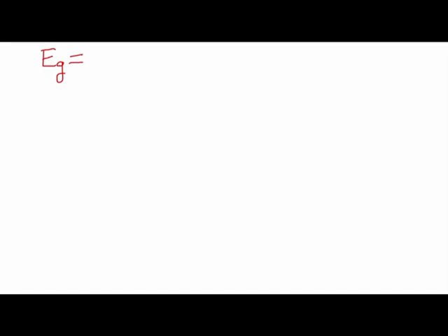That is 541.67 volts. So for the same generator, if instead of lap connected, it is wave connected, then the number of parallel paths for wave connected is equal to 2.